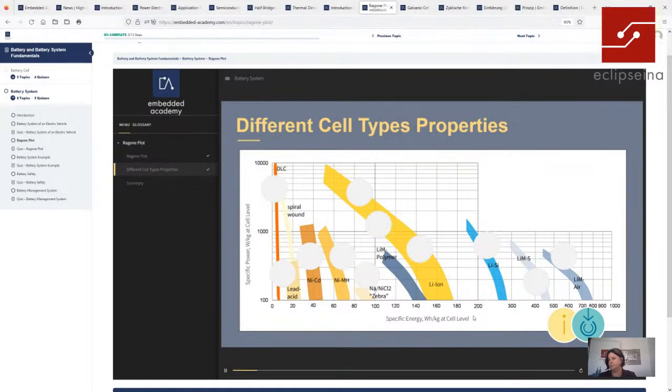Lithium-ion was very expensive, and hence nobody considered using lithium-ion batteries in large-scale automotive applications. But all in all, lithium-ion batteries provide a better energy density and cost reduction in the long term. Dozens of materials were developed and established lithium-ion batteries as the highest class of batteries, starting between 100 and 200 watt-hours per kilogram. So you get different information for the different battery types, for example here.